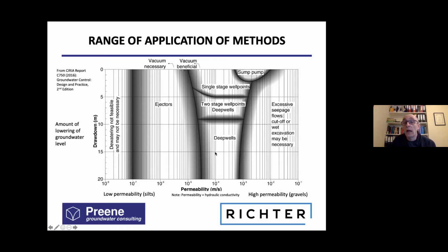You see, this is well within the deep well zone. And that would mean that as a designer, I would be thinking that in all probability, the deep well method, if we're going down the pumping route, is the most appropriate method. This does not replace the overall design process. It does not mean we don't have to do more detailed work, but it's the starting point to direct the design.